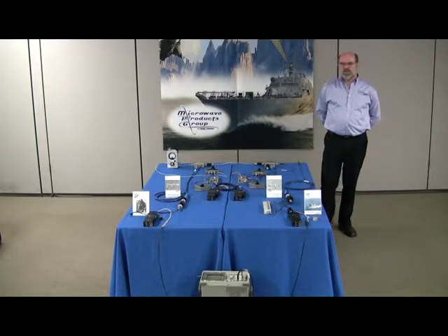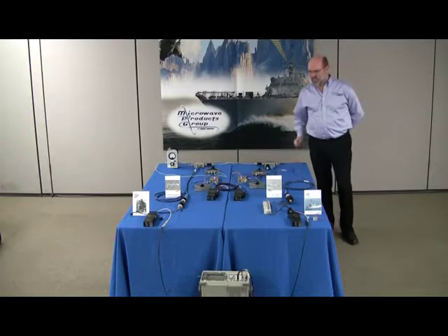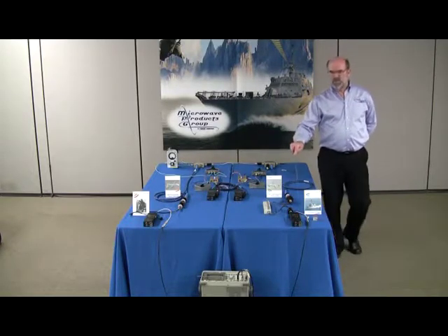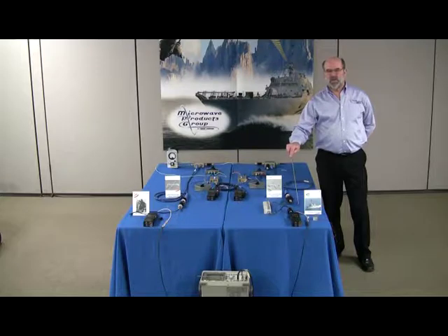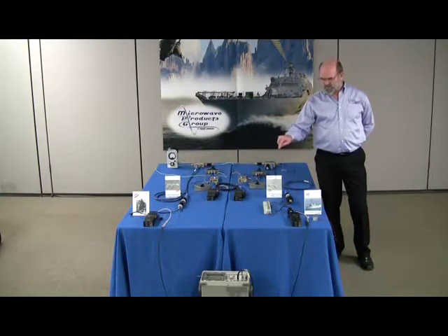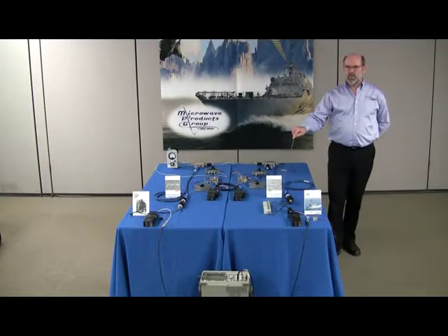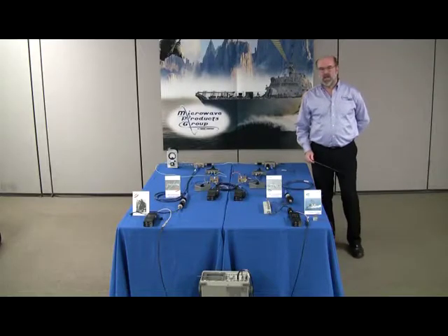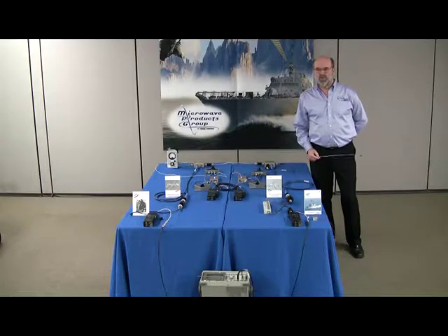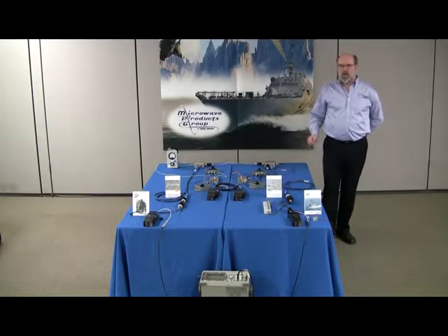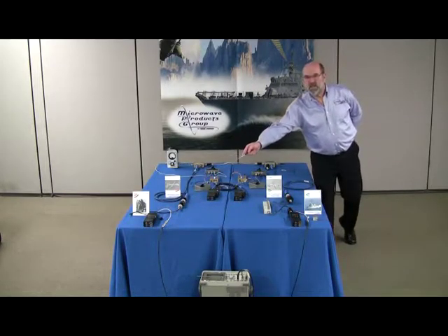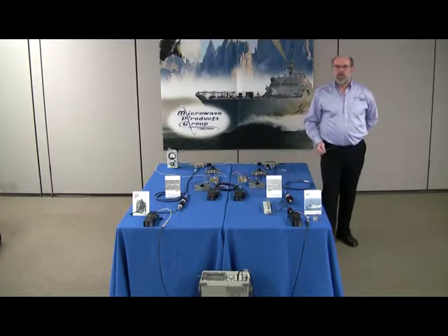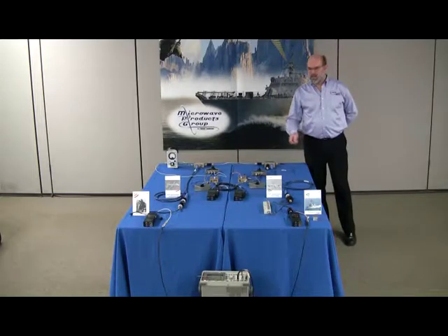To measure the UAV's uplink victim receiver sensitivity, we will transmit from the uplink transmitter at a fixed output level, followed by a variable attenuator. The amount of attenuation applied with and without Cosite interference mitigation required to yield 12 dB SINAD at the downlink receiver will determine the UAV's uplink or victim receiver's sensitivity with and without Cosite interference mitigation.